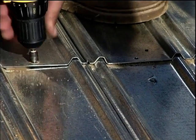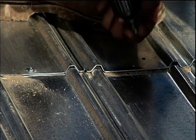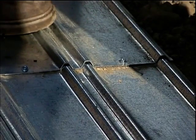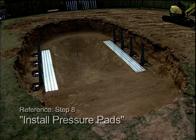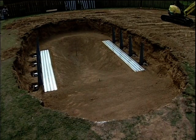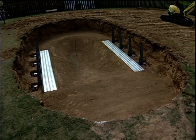Once this is completed for each of the pressure pads, connect the ends of the pressure pad to each other with 4 10 by 3/8 inch long screws. Please reference Step 8, Install Pressure Pads. Now you're ready to move on to the bottom rail installation.